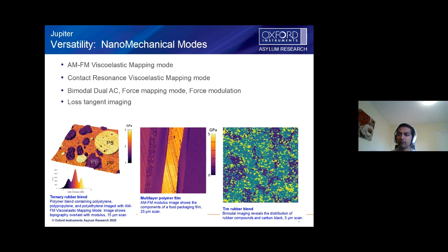Thank you. We have two more questions in the queue. The first one is, can we do a conductive AFM measurement in the AFM we have at the UTD clean room? The UTD clean room needs to purchase the conductive AFM tip holder. It's a relatively simple and inexpensive upgrade. So the short answer is no at the moment. Yes, if you acquire the conductive AFM tip holder. And if you send us a note or an email, I'm happy to talk about this in more detail. But you just need the conductive AFM tip holder to be able to make this measurement.